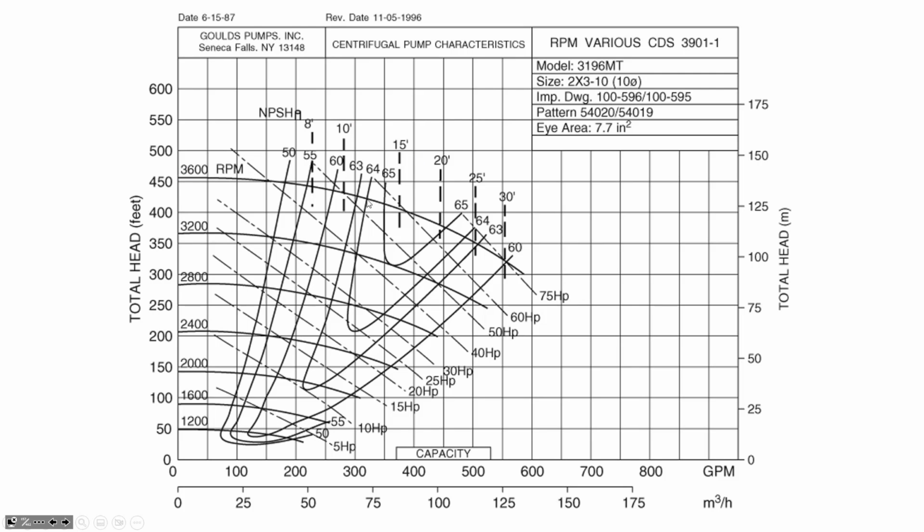So the shape of this curve follows that same trend demonstrated in the video: you have a cutoff head, which is the amount of head or pressure that is going to cause a flow rate of 0. But if the pump isn't having to add that much pressure, then it can move the water through the system and generate a positive flow rate. So as the flow rate increases, the head that it's adding to the system decreases. That's the first trend I wanted to share with you.